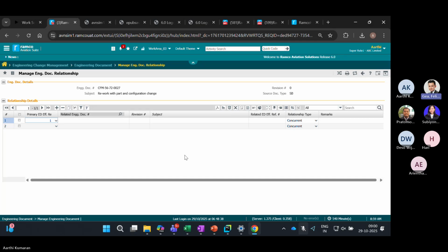So we also have a planning data sheet, or PDC, and a manual, we call it CMM, component maintenance manual. Between the CMM and PDC, the revision must align. Yes. If there is a new revision, we need to update our PDC.